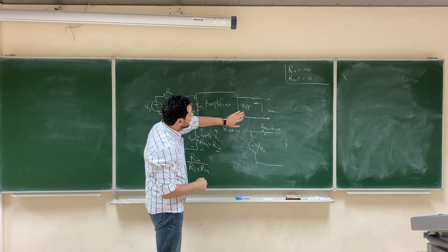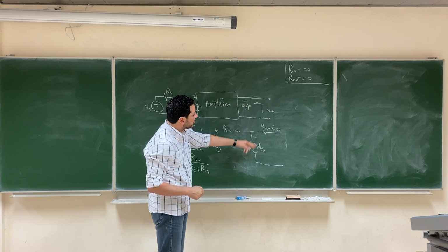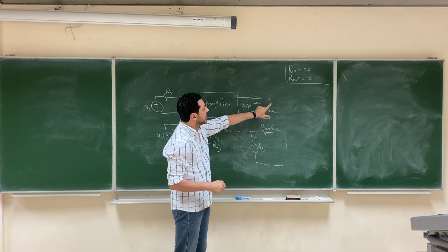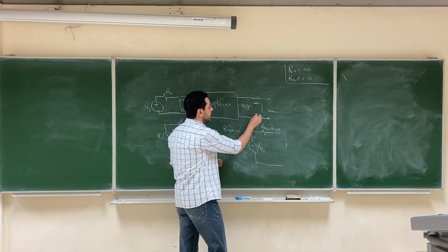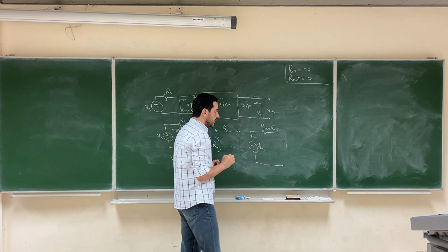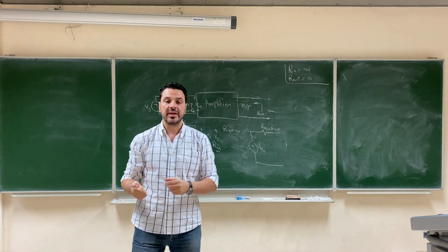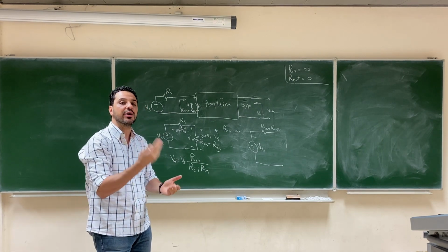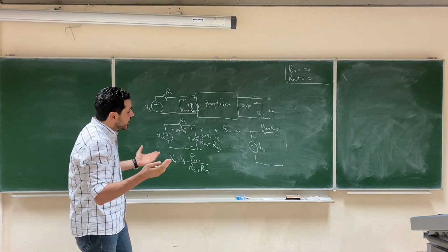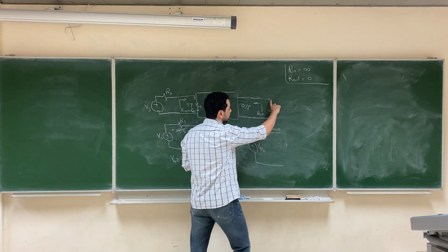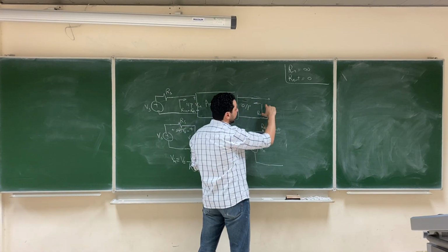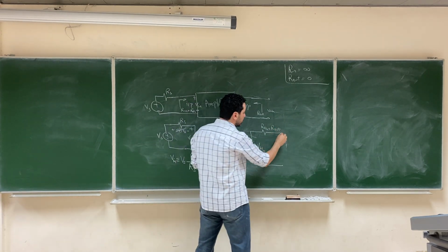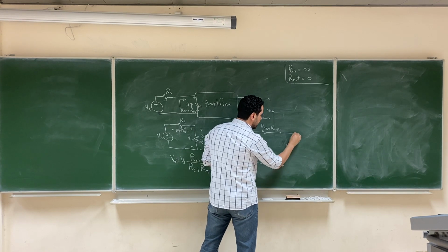So you can represent the amplifier as an equivalent circuit of R Thevenin and V Thevenin, where V Thevenin is the output voltage under open circuit condition and R Thevenin is the output resistance. The question now is, is it good or bad to design this output resistance to be low? Should we design the output resistance to be high or low? Again, imagine that you are going to connect the terminals of the amplifier to a load, like a TV, like a computer, any load. So you are going to connect it to a certain load, RL.